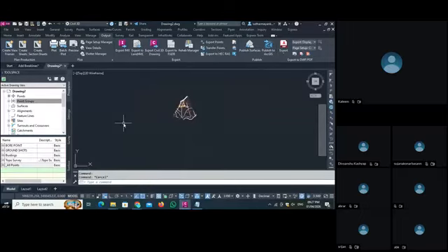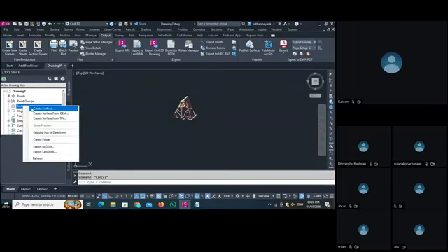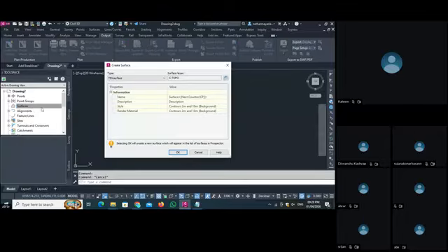The first part, see, after creating points and point groups, we go here to surface. We are right now in the Prospector tab. As we select the contour, surface, you can see again there is nothing here in front of the surface. Now what I do, I right click here and create a surface. See, as you select create surface, you can see a surface dialog pop up. Here you can see the type.